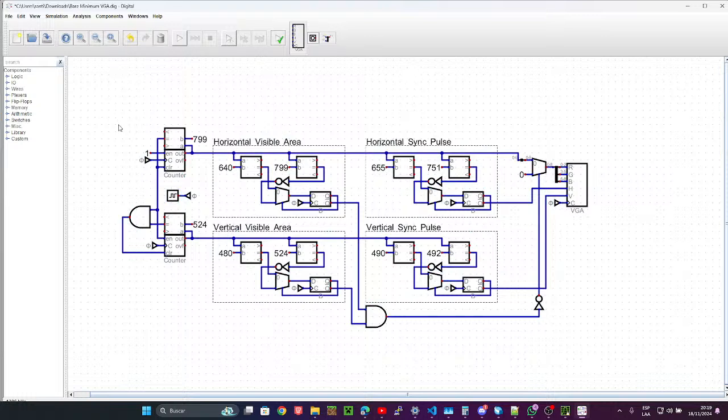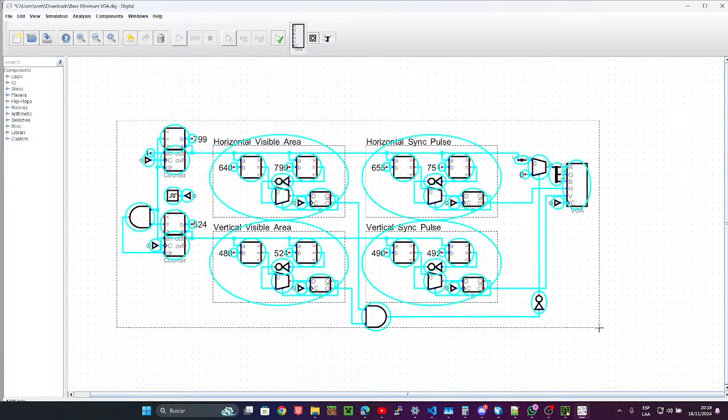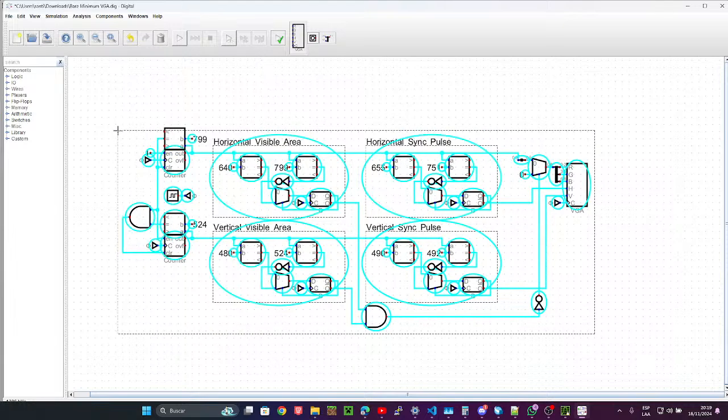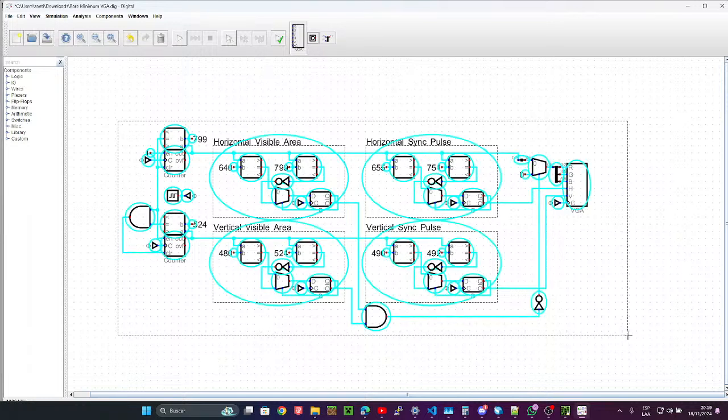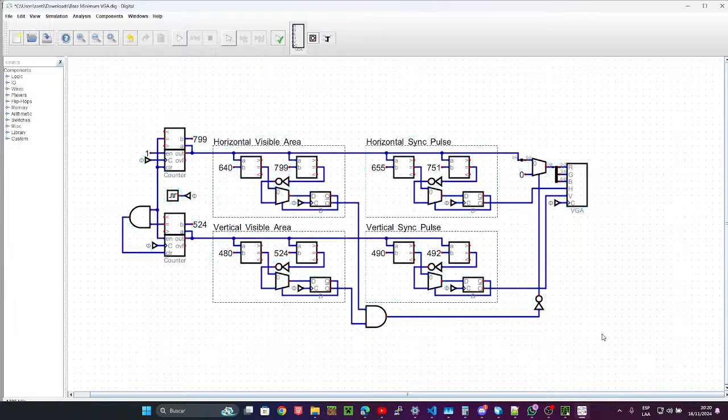In each block that you call 1 pixel is 8 by 8 pixels on the screen, right? What if you had one memory location for each of those 80 by 60? You call that a character, and then for each of those locations, you can define which set of 8 by 8 pixels stored on a secondary memory is displayed.